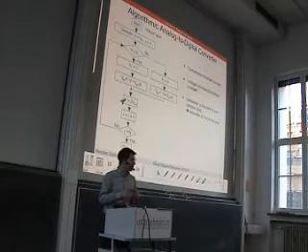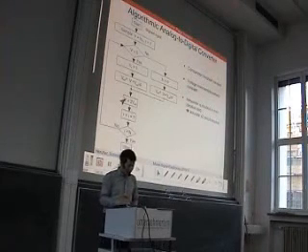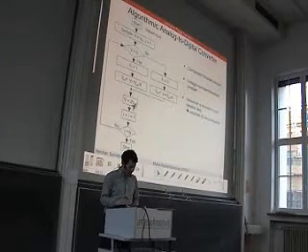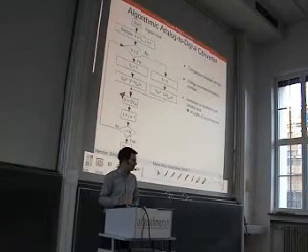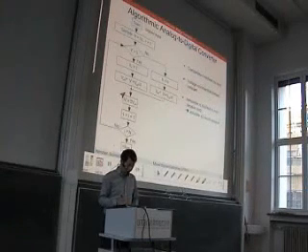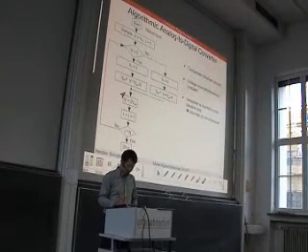There I explained that we scale the internal voltage, the remainder or the quantization error, back to the original voltage interval, and then we proceed with the next iteration cycle in this algorithm.